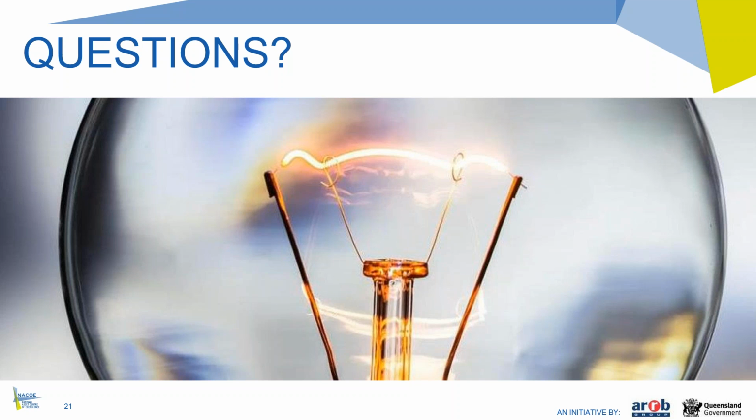It's going to be no different in the new method, so there will be the option, if there's no weigh-in-motion data available, to assume some values or assume a traffic load distribution. We're working on some separate guidance to help designers come up with some assumed values for different situations. That information will come out in the coming months, I'd say. So there'll be a fallback position if there's absolutely no other data available which could be used for this method.